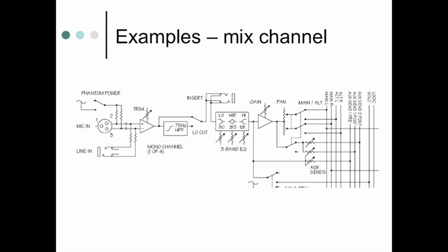So now the signal's still passing through here clean with no reverb, but it's also now going out send 6, depending on how much you want to send to it, right? You can send a little, send more, send a lot. Goes to the reverb, and then the reverb actually can come back in to an unused channel strip and call it your rev return, reverb return. And then this blends together based upon how you set your faders with your non-reverb vocal. This is all reverb vocal. You can blend how much you like, how little you like, and then it combines into stereo, goes to your final mix. This is all signal flow that you do in the studio.